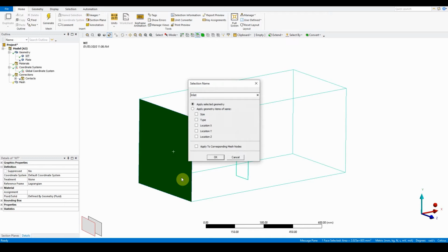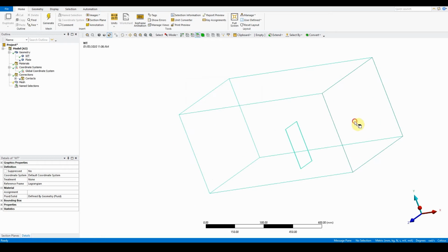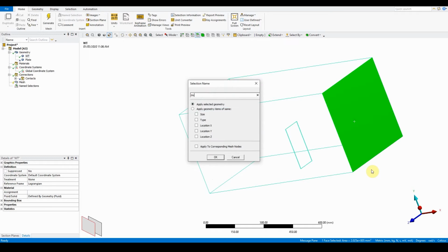It's very important that you correctly spell all the name selections, because the algorithm looks at the terminology and defines the boundary condition. If there is a spelling mistake in Inlet and you transfer it over, the Fluent part won't recognize the name and therefore will have it as a default wall, which can have a huge problem on your simulation. So Inlet, and the back end is Outlet.